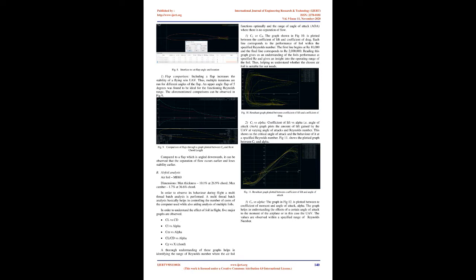4. Design methodology. A. Initial design input and parameter calculation. In order to determine the dimensions of root chord, tip chord, and span, we have chosen the approach of achieving a specified cubic wing loading. Cubic wing loading is the ratio between the total weight of the airplane to the total wing area. For the amphibious application we chose a wing loading of 20-25 ounces/sq ft, i.e. approximately 20 WCL, wing cube loading.